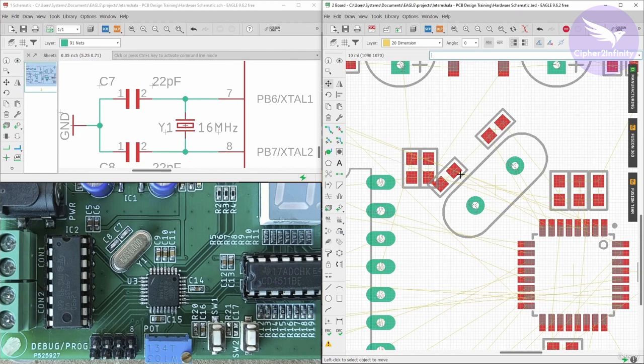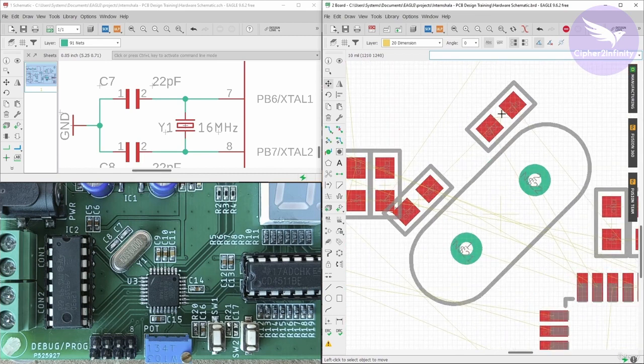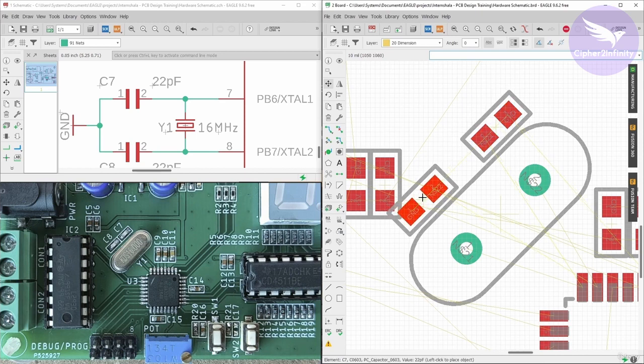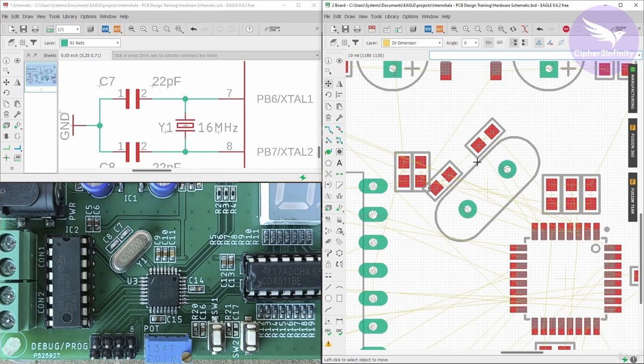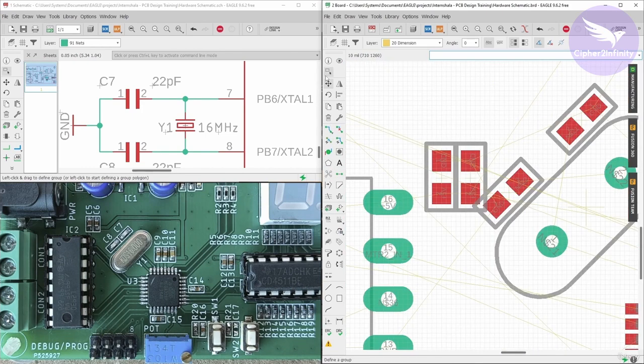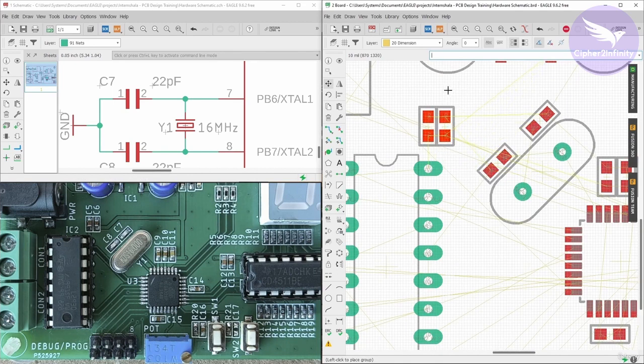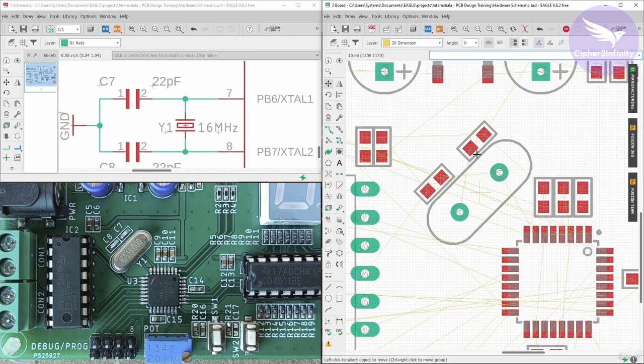We should place the component at the appropriate location, and later we can think about how exactly the layout is looking. Okay, so in order to make the layout nicer, you can place the components accordingly. So I'm just going to place these decoupling capacitors near this crystal, and you can see here there is an overlap. So I'm just going to move these capacitors like this. I will group them, and later I will place them here. All right, so again they are actually near to this IC only, and I will just move this capacitor like this.